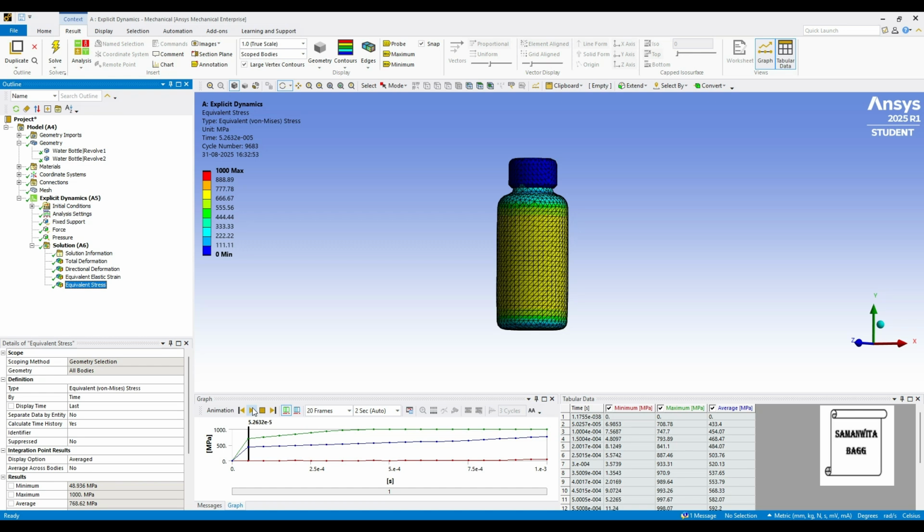Now if you analyze for 20 megapascal, say, for all the three bottles, that is of three different materials, you will not see a bursting in any of the three, because the minimum value where the bursting was not taking place was for copper was 20 megapascal. So if you apply 20 megapascal or 10 megapascal over the bottle surface from inside, irrespective of the three materials, your bottle is going to remain safe. If you ask me what is the safe value, then it is say 10 megapascal, 5 megapascal or 20 megapascal. But the moment you change it to 30 megapascal, it will burst open for copper.